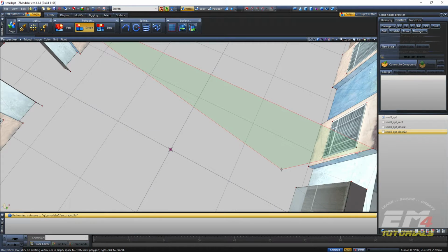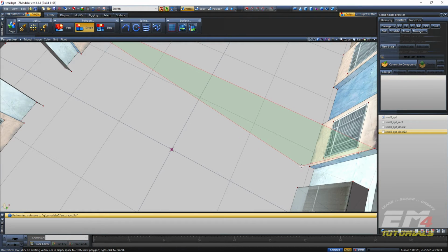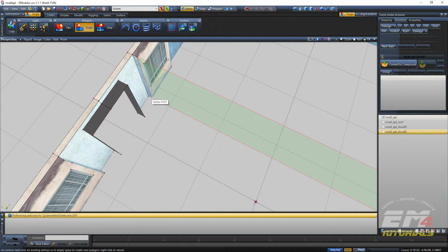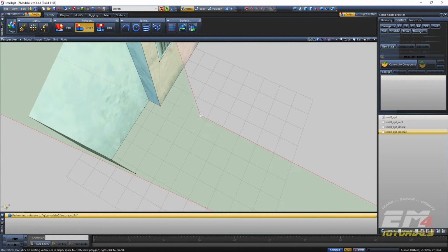Now, to make a three-dimensional polygon, we have to select multiple points. So we're going to select the bottom corner here, and the bottom corner here, just like that. If I zoom in, you can tell I'm going for that corner because the polygon and the intersecting lines or edges will highlight blue. So I know that I'm going for that one as opposed to that one, right? I just want to make sure that when I click, the polygon that makes up that vertex is highlighted.